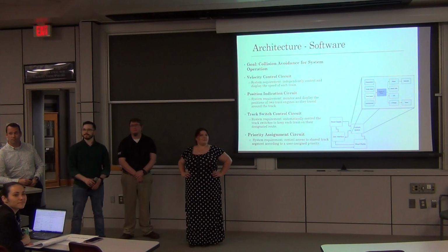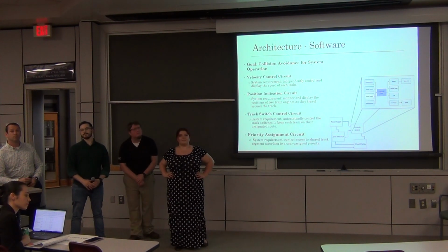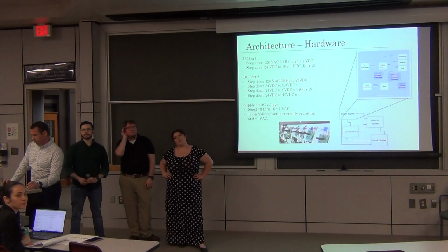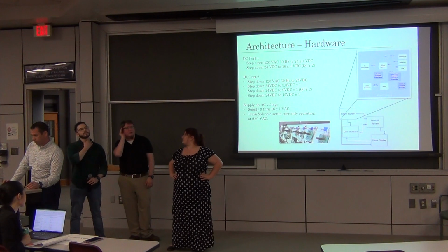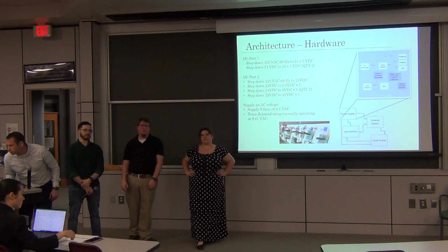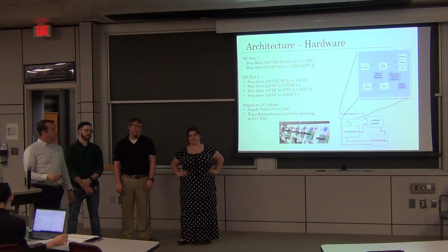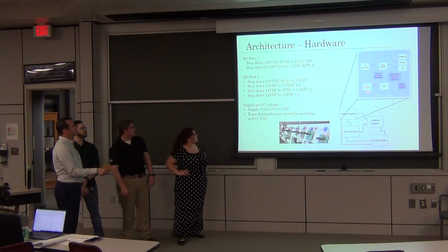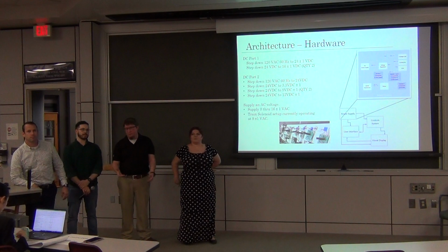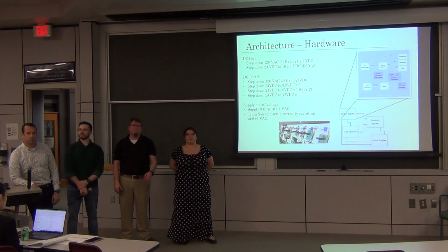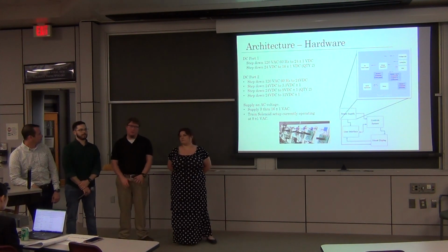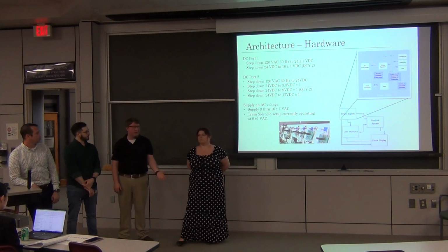I have a question. On I think the first 2 or 3 slides, you mentioned that you use an AC to AC converter step down. What did you use that for? It was used for the solenoids and relays, so that's the only function of the AC to AC. It steps down 120 to 9, 16, and 24. We only really use the 9.6. Essentially it drives the relays, which drive the solenoids, which allow the trains to switch between tracks. So from 60 hertz to 60 hertz? Yes, sir. Essentially this is a straight step down, so 120 to 9 or 16 or 24.